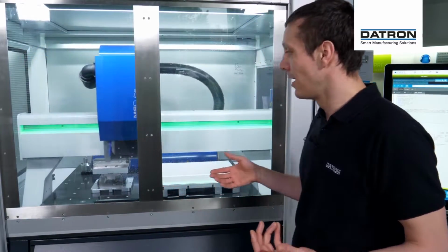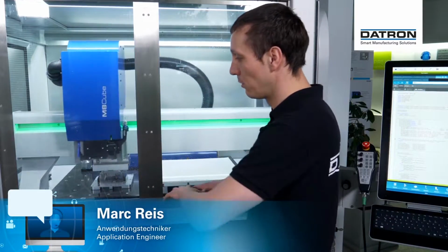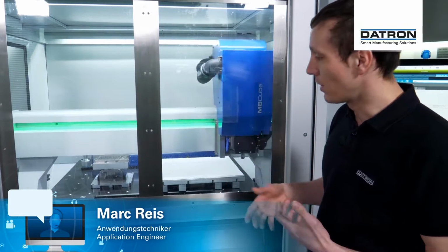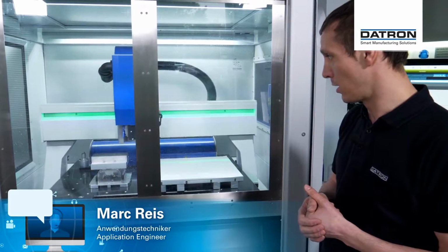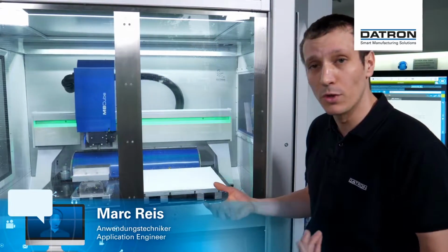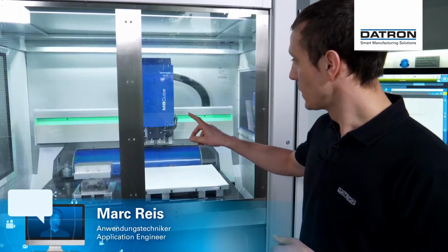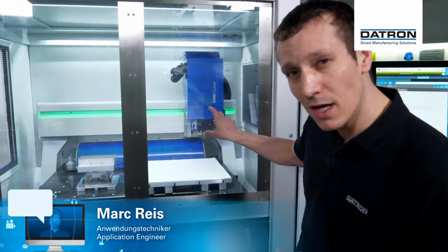As this is a gantry style machine, the chips will pile up on the table. So in order to get process stability, we need to make sure that most of the chips are out of the way and don't interrupt our milling process. You can see that little blow-off nozzle on the left-hand side of the Z-axis.